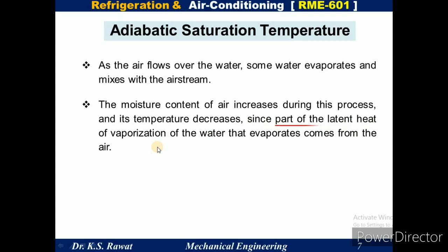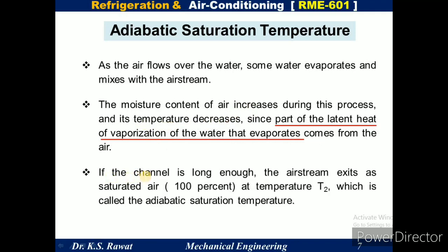So this is a very important point, and I will discuss it in the upcoming lectures in the topic of evaporative cooling. For the time being, you have to remember that when the moisture content of the air is increased, its temperature is decreased. If the channel is long enough, the air stream exits as saturated air, 100% relative humidity at temperature T2. So the temperature of this saturated air is known as adiabatic saturation temperature.